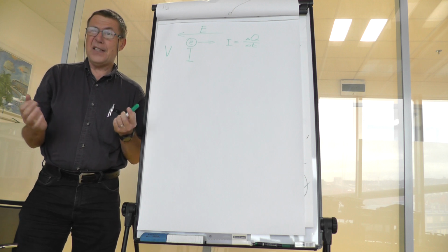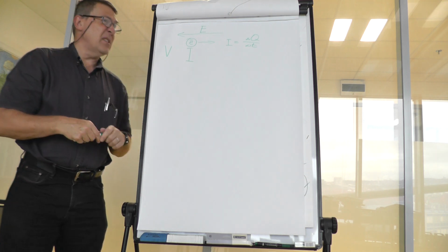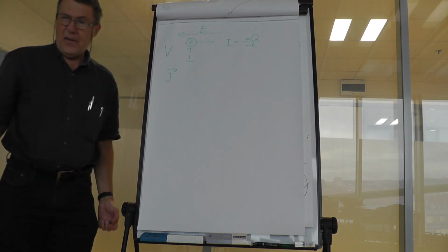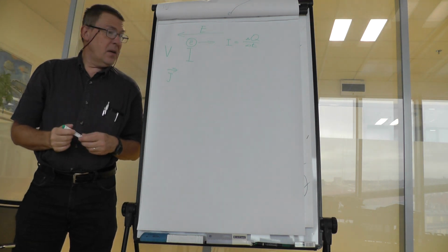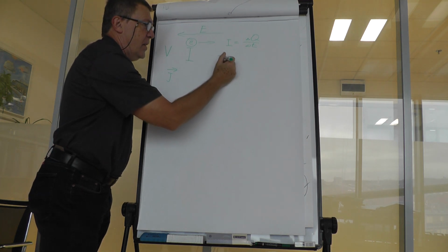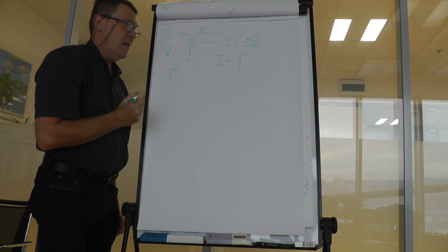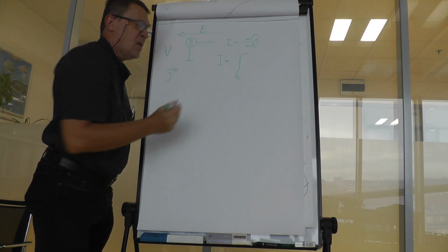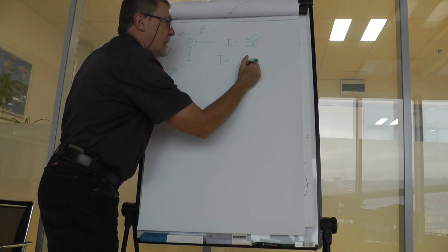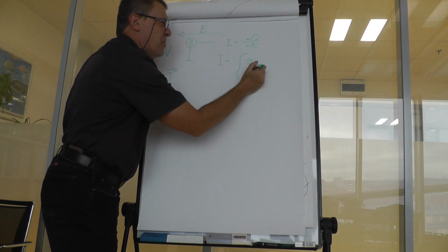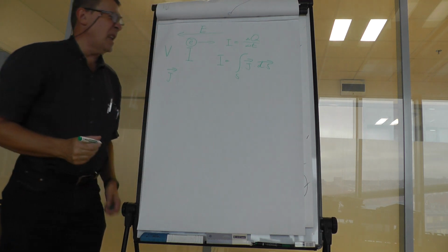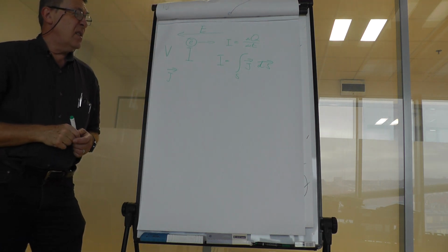And this flux density is called current density, J. It is a vector, and we can find electric current I using an integral over a surface through which the current flows, where the integrand would be the current density J multiplied by the surface element of that surface.